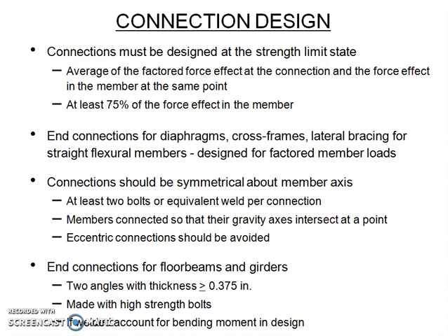Number one is that we are designing to the limit state. So the average of the factored force in the connection and the force effect in the member at the same point is what is calculated, and at least 75% of that force effect in that member. So this 75% of the force effect in the member is essential.